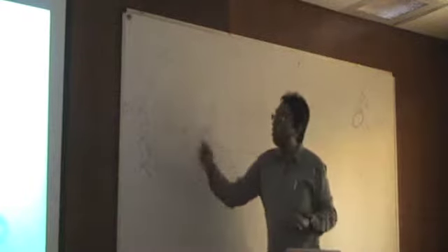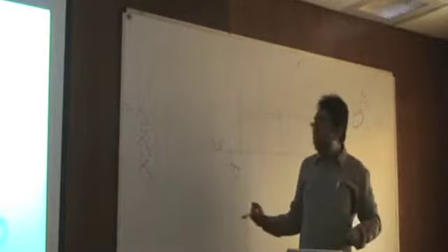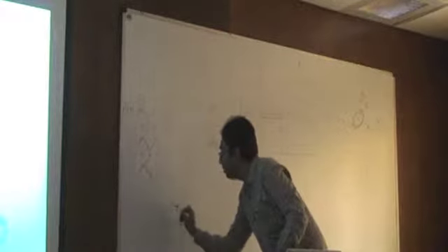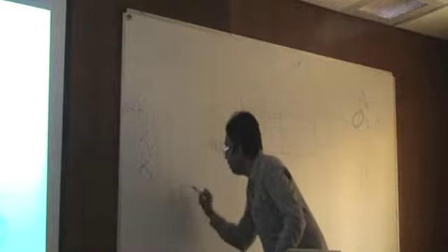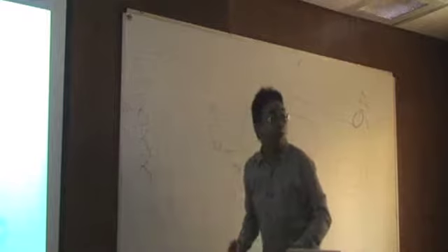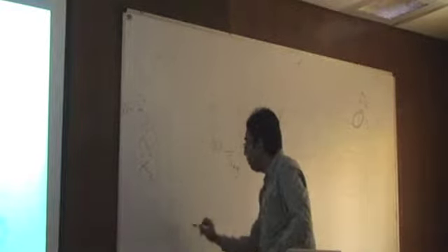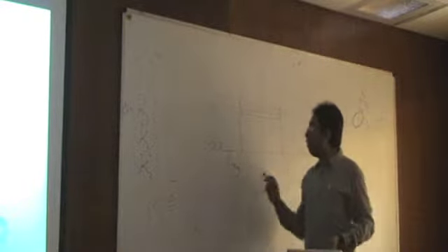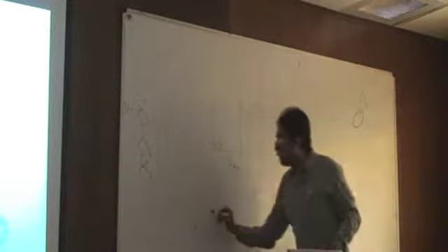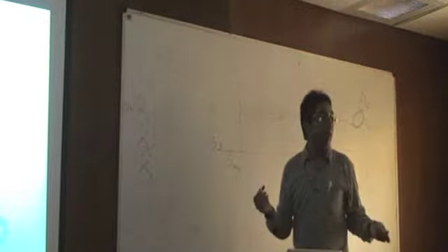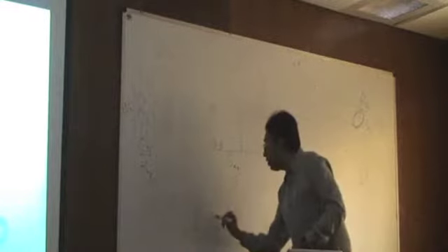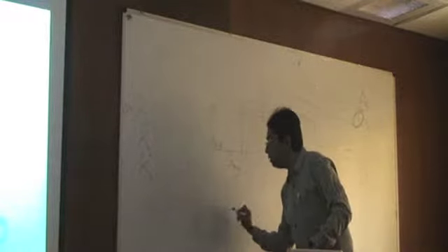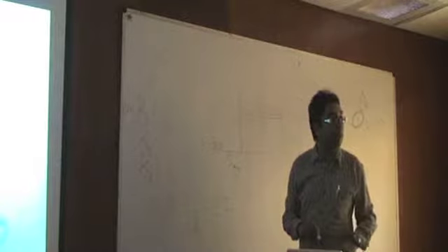It's a relationship between kappa 2 bar and your M2, which is in turn defined as the partial derivative of your one-dimensional strain energy density with respect to kappa 2 bar. So this is your bending moment. If you were not taking this into account, in the case of an isotropic beam, you would have just got this to be EI2. This is your bending stiffness, right?